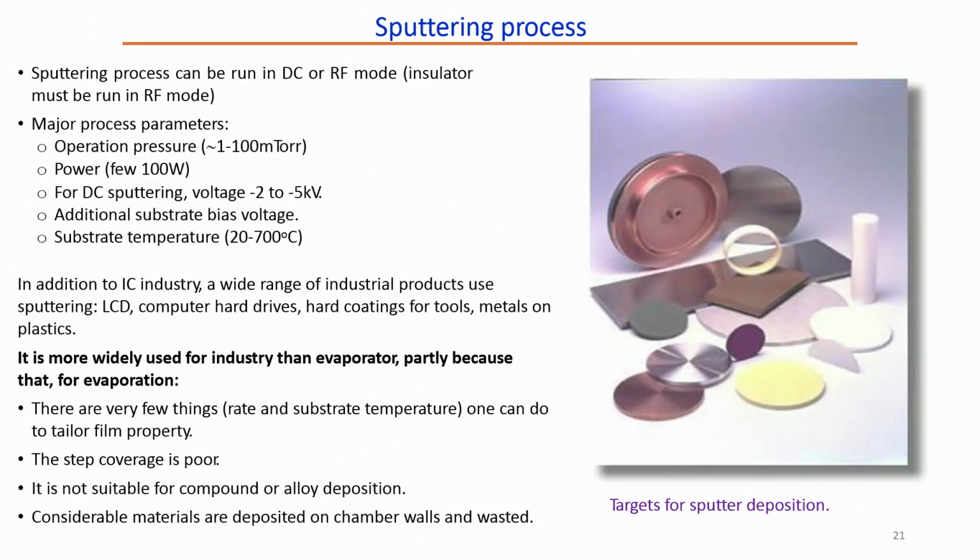So, sputtering process, like I discussed earlier, can be run in DC or RF mode. Particularly when we are using insulator, we have to use RF mode.